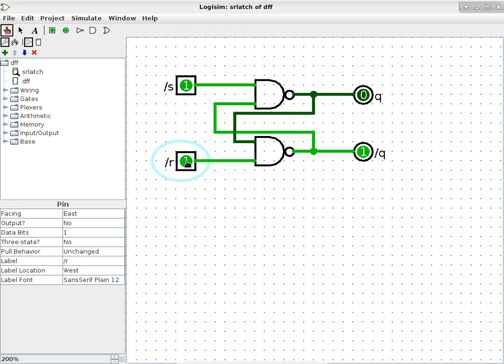So you have a 1 coming out of the top NAND gate, and a 1 coming out of the bottom NAND gate. Those are being fed back to the inputs, right? And then what's going to happen? It will initiate the change of the gates changing. But from the moment those changes occur, it will take a propagation delay for the actual outputs to change. And they go back to 0, and go back to 1, go back to 0, go back to 1. So this circuit will start to oscillate.